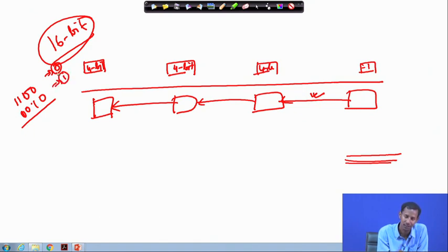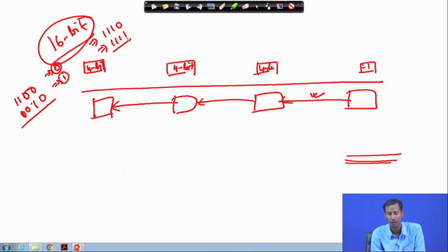Whenever this is 0, I get 14, and for this I get 15. So from the beginning I am calculating both 14 and 15. Now, based on the carry output bit of this LSB side, I will choose which value to select.